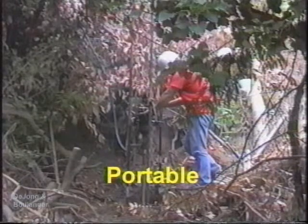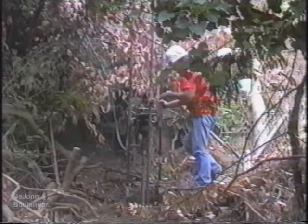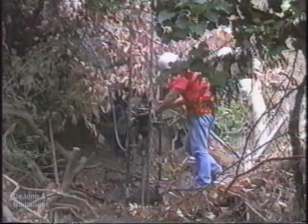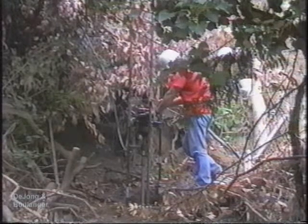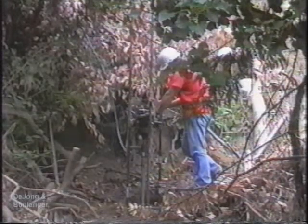Portable rigs can be partially machine-operated, as shown here, or operated manually. These rigs typically have a depth limit of about 25 feet, depending on the subsurface conditions, and are used when access by an off-road rig is impossible and the expense of a helicopter is not justified.